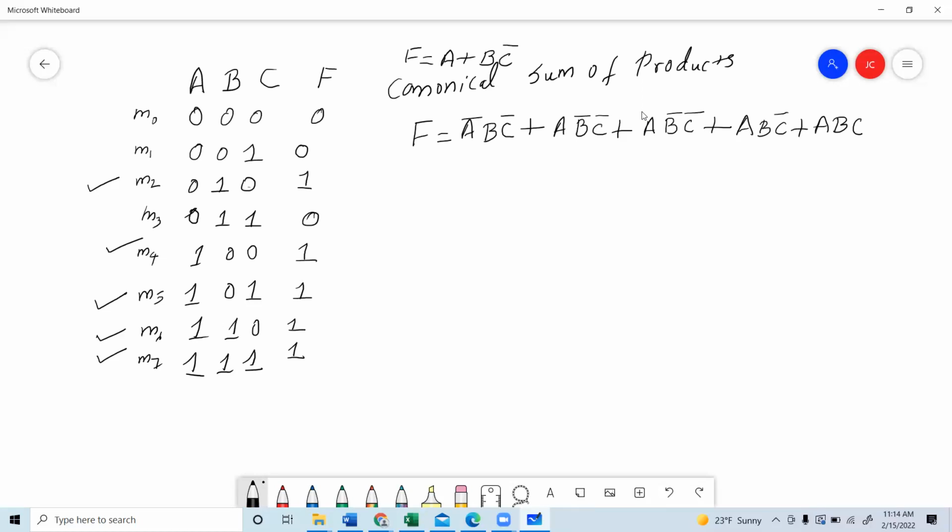Okay. So, but this is the expression I told you. So how to reduce this expression: A bar, B C bar, and here I can find A B bar as the common term, or what is the common term here? Did I make any mistake? Sorry, here there's no C bar. I made a mistake. There's no C bar here, right? Because if I look at this expression, which is for the output being 1, this is A, B bar, and C, right? I put a C bar here. That is not true, right? This should not be there. So I'll use the eraser to eliminate this.